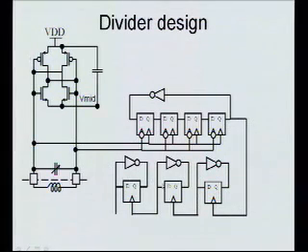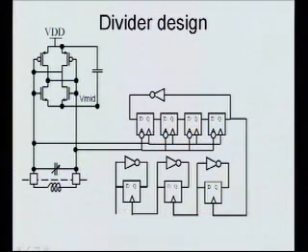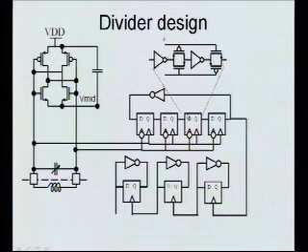Now, it's a little funny. Why did I bother with this weird divide by 8 thing when I could have just gone straight into one of these and immediately started dropping my frequency? And the benefit is only clear once you actually look at, so that's my signal flow, the guts of one of these guys. Basically, this D flip-flop is just 2 inverters with 2 switches. So each time one of these switches opens, an edge propagates to the next inverter.